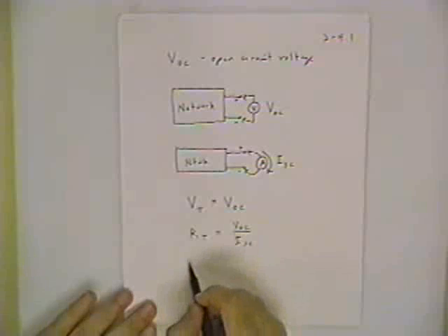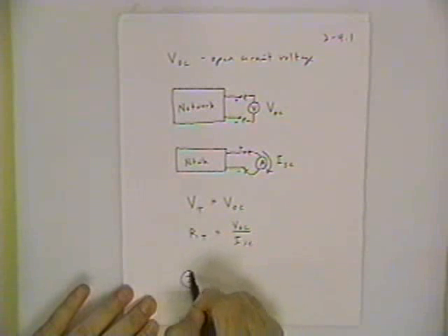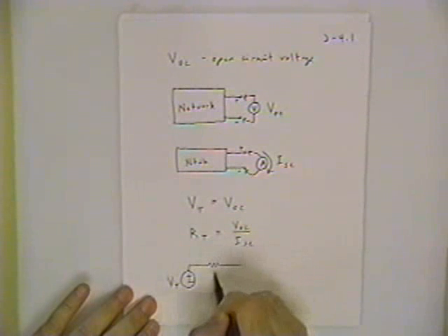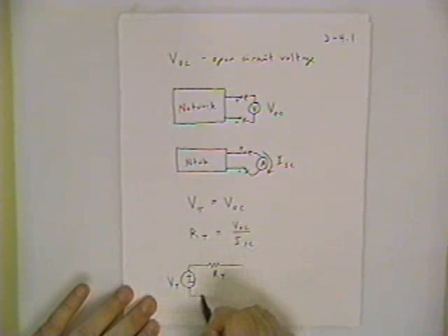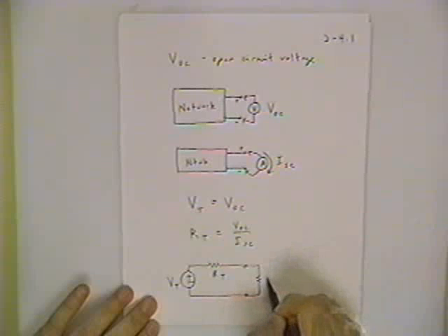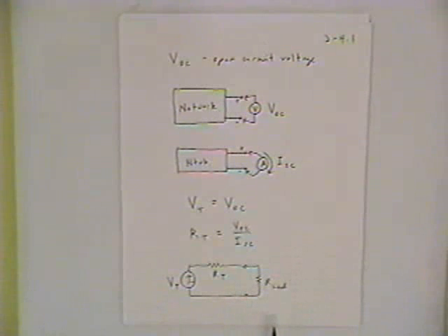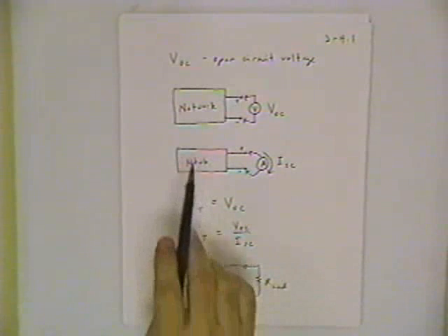And so now we have the two pieces that we need for our Thevenin equivalent model, VT and RT. And we can attach whatever our load resistor is here and complete the calculation. The advantage of the Thevenin equivalent is that this equivalent network could have, as I showed before, multiple components, lots of sources, lots of resistors, other elements.